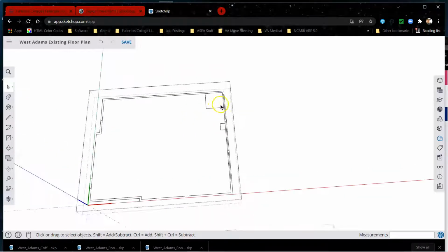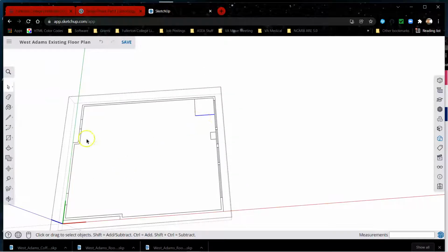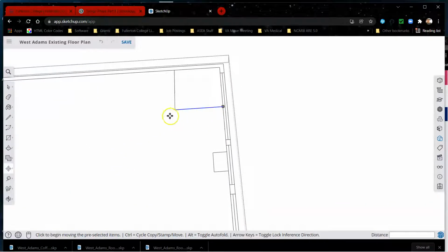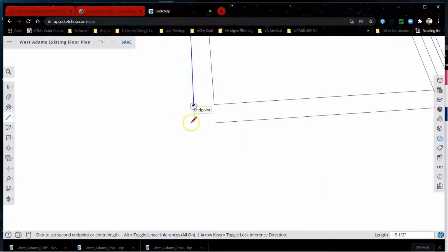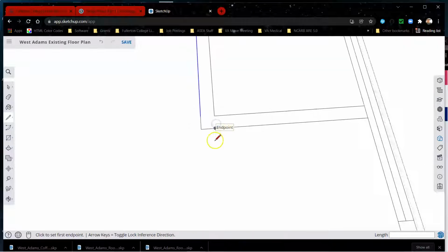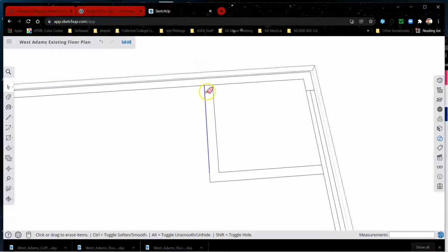And so instead of using the offset command, because it's going to offset all of this, I'm just going to use the move command and hit Control and type in 6. I'll do the same over here. Select, move, the letter M, tap Control, 6. So SketchUp already kind of intuitively knew I was going to connect these lines. Let me erase these lines right here.